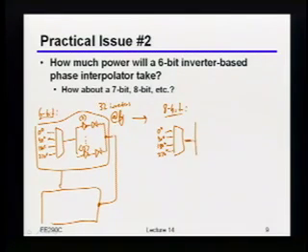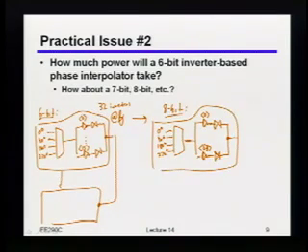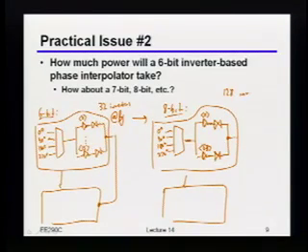But now if I look at how many legs I need inside of that programmable width inverter, because I wanted that extra resolution, now I need basically 6 bits of resolution inside of that programmable width. So now this has to go to 63. And again, of course, you have the same block repeated below. And so that's why we got 128 inverters now at F.